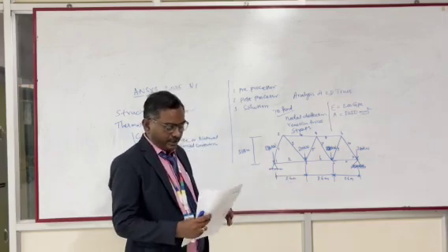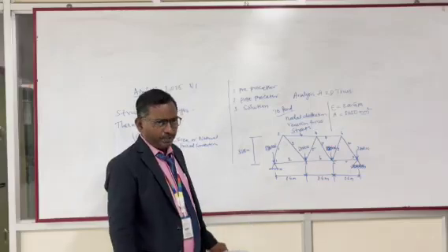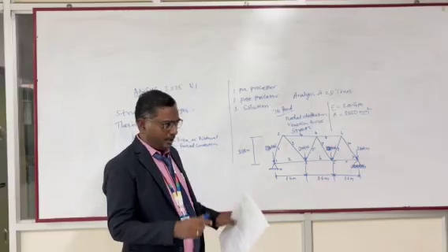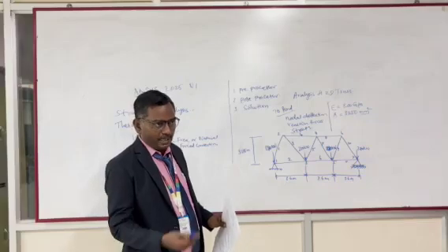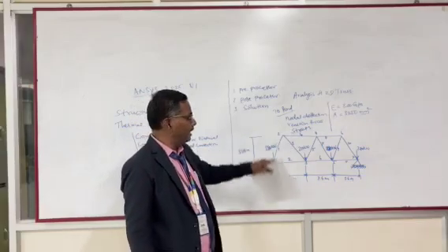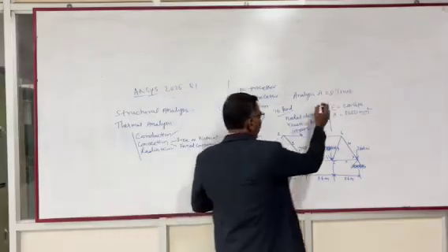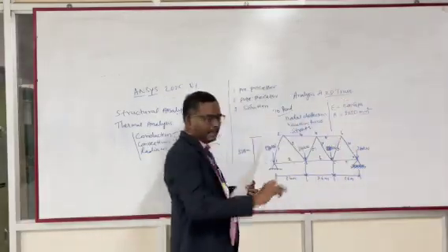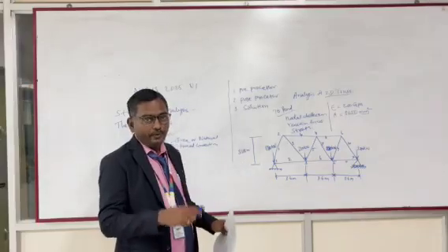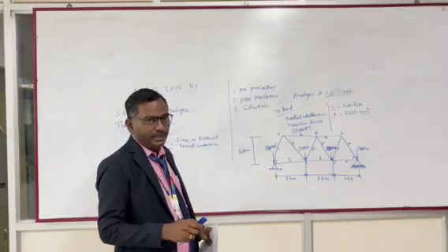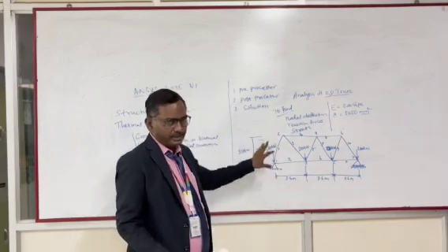So the Ansys software itself, we can draw the diagrams. The first step of the Ansys software: first we are going to change the directory. As our exam Ansys problem name, we can give it as the directory. You can change the directory, select it, and create one folder. After creating that folder, in that folder itself, we can solve all the problems. Okay, this is the first step.